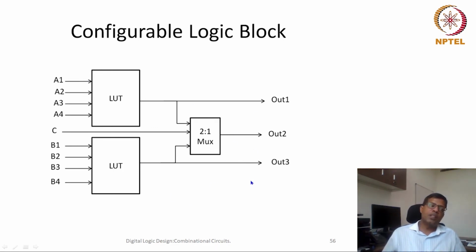So the idea is that you will feed the content of your truth table in the lookup table memory, and this lookup table will give you the output corresponding to one function, whatever we would like to design or program. Okay, so this way these FPGAs can also be used as a programmable logic. Now with this we will close this lecture. We will also see how the sequential logic will work, and then we will have one more lecture explaining how this programmable logic can be created.